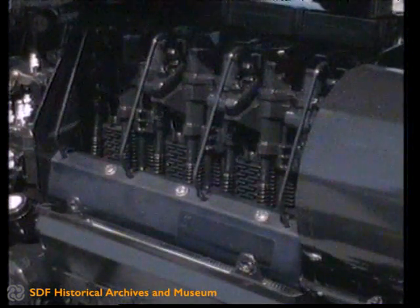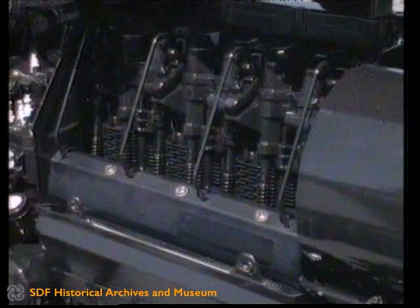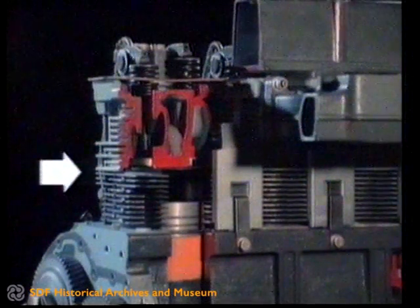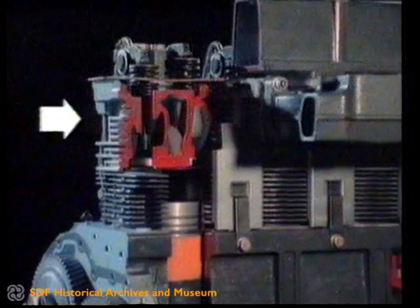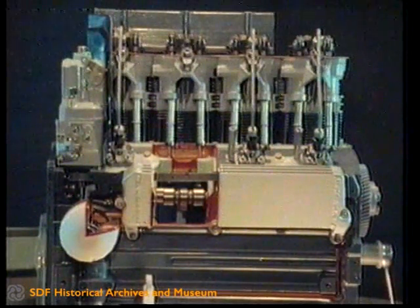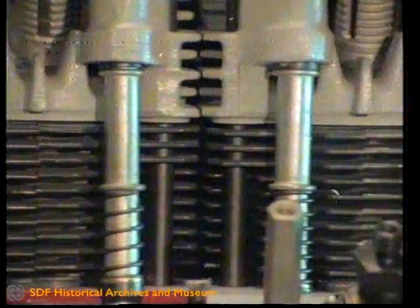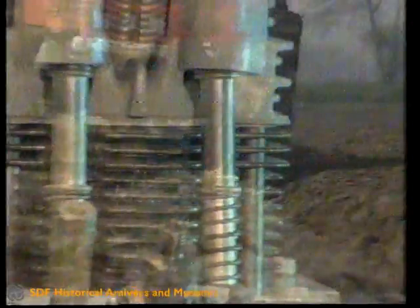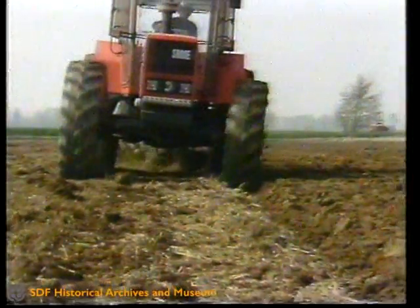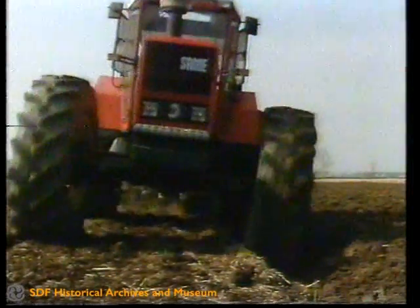The efficient discharge of the heat from the cylinders to the cooling air is an essential condition for preventing overheating of the engine. To this end, in SAME engines, the heat exchanger surface of the finning has been provided so that where the temperature is highest, at the cylinder heads, this area is greatest. The finning on the cylinders has a much greater heat exchanging surface on the right-hand side of the engine, where the greater heat is generated. This has enabled the operation of the engine to be pushed to the higher temperature cycles without any risk of localized overheating of the engine, with the advantage of a much higher thermal efficiency, resulting in an exceptionally low specific consumption.